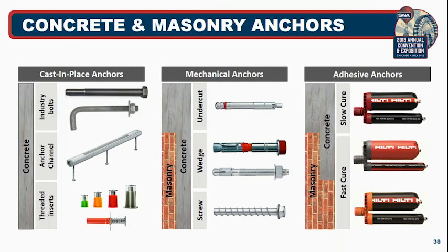You also have mechanical anchors that are suitable for concrete and masonry applications. These include things like the undercut anchors that I was talking about, wedge-type anchors, which use an expansion principle to actually set the anchor and distribute the loads, and screw-type anchors, concrete screw-type systems. Wedge anchors have been around, I guess, since the 50s or 60s or so, right? And they're very popular in the industry right now.